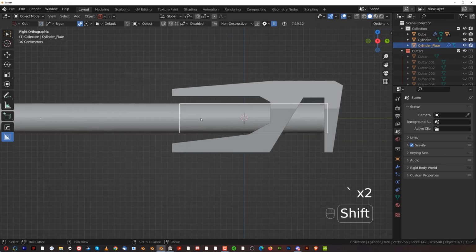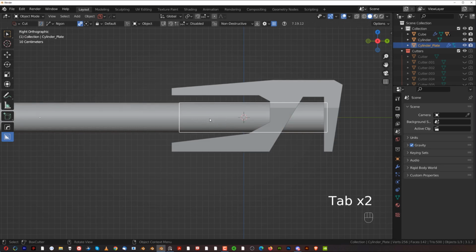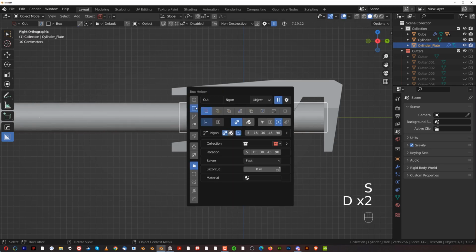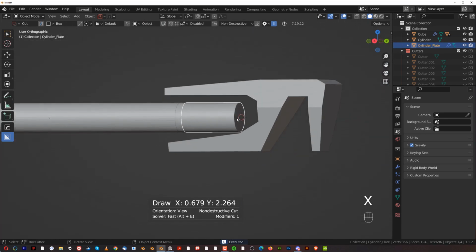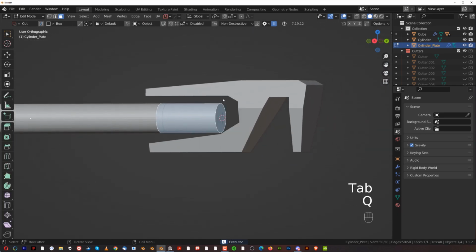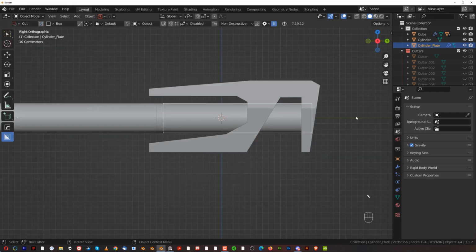This could be a bit thicker, so we could thicken it out. Maybe even slice this. So slice it somewhere here with X. The reason why it collapses is because we didn't apply scale, but we can always go to modifiers and solidify it further here. Okay, cool.